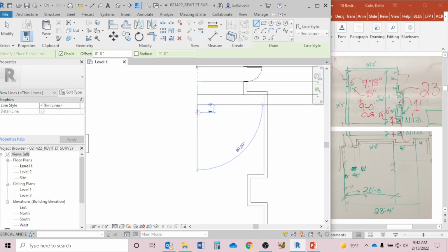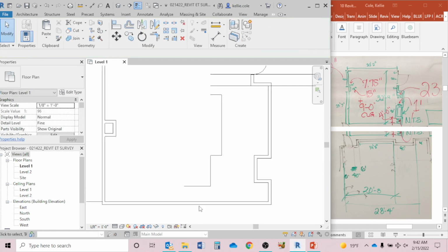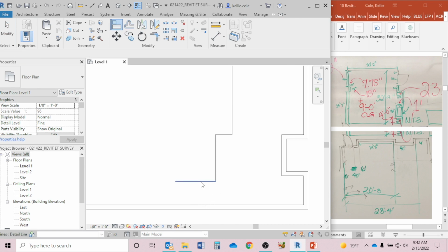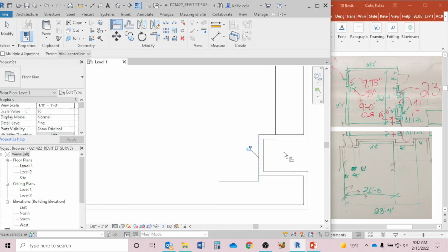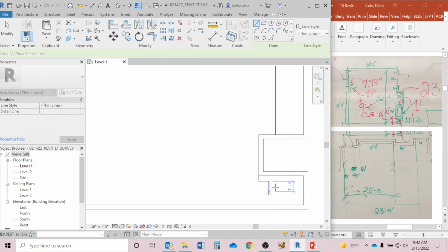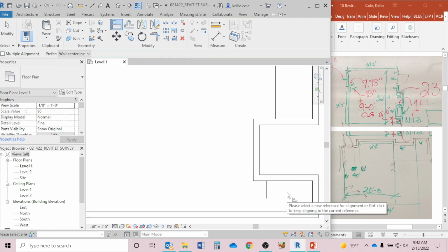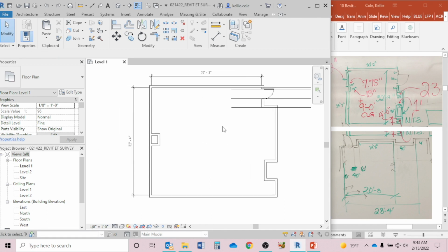So every time we have detail lines to guide us, these walls are going to align to the face we measured. Oh, that wall is pinned. It won't move, right? But I can select this, align, align, align. If this moved back, I would align that shaft like this, right? It fills out beyond the interior dimension we took. All right, I'll undo for all of that. Okay. So let's continue fixing this wall kind of piece by piece using dimension lines or offsets. Then we're going to move on to a stair.